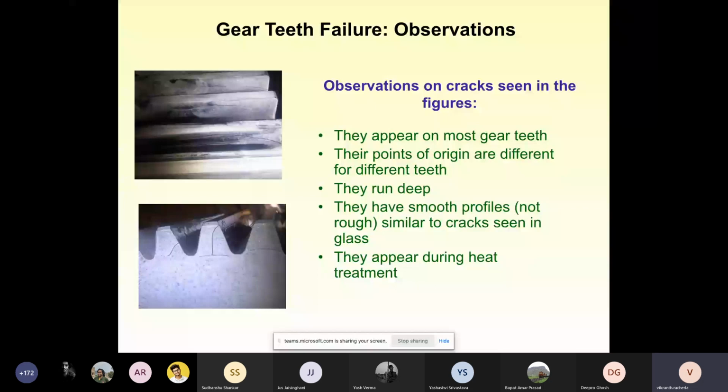And where do you think the stresses generated would be highest? In this case, what causes the stress within the material during the cooling process? The outer tries to shrink, but the inner is still hot, so it causes stress. Yes, basically the outer is cooling and wants to shrink, but the inner doesn't allow it to shrink. So the thermal gradients are the ones which cause the stresses. These are all thermal stresses which are getting generated within the material.